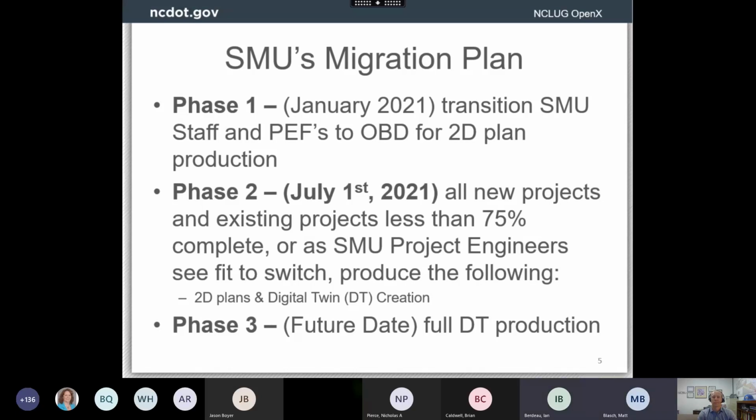I have another question also. Can you fake an MSE wall with a wing wall at the abutment? So similar to faking the approach slab in, is an MSE wall able to be faked in using a wing wall at the abutment? So you could fake it, and I think Oak had tried to convince us to do that on one of our test projects. You can use an abutment and sort of fake it in place.